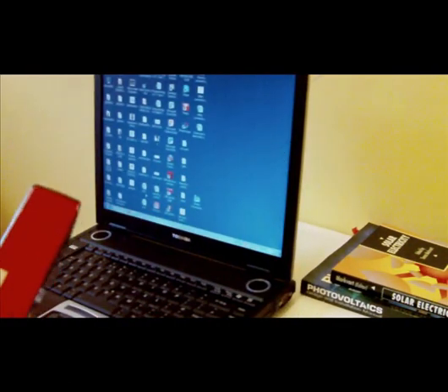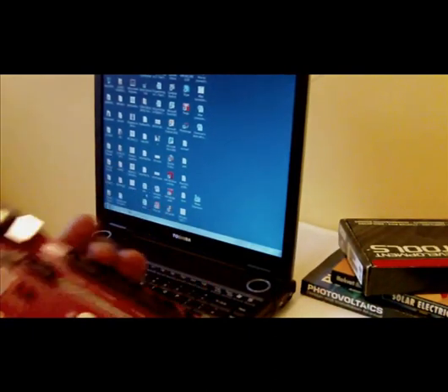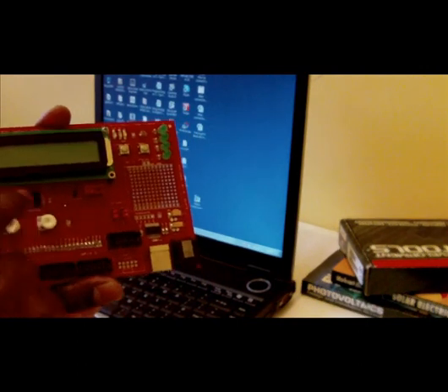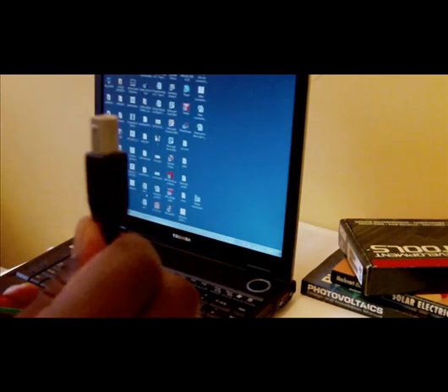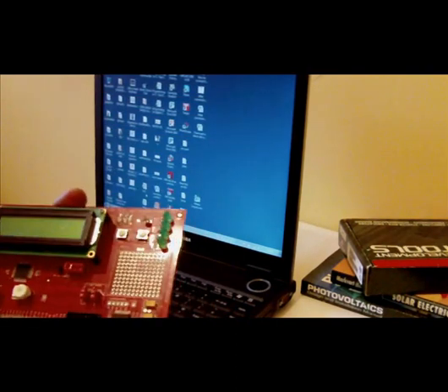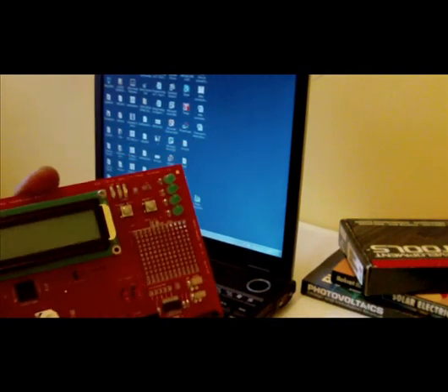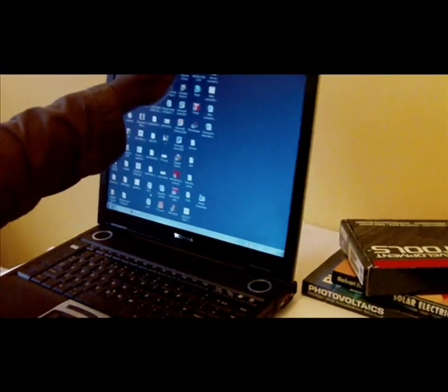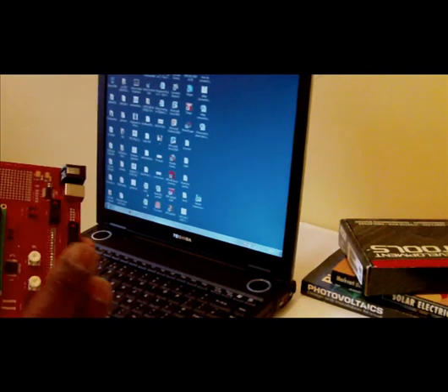Normally you will do that by using one of these fancy hardware tools, a programmer, which is expensive. I have done away with this by implementing a bootloader technology, which I have programmed into this chip. So you can only use a USB cable to download it. You can use a programmer if you've got one, but if you only have a USB cable, a board and a laptop, you can start doing some serious projects.